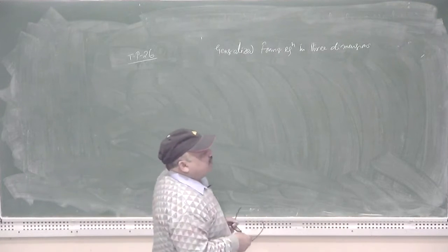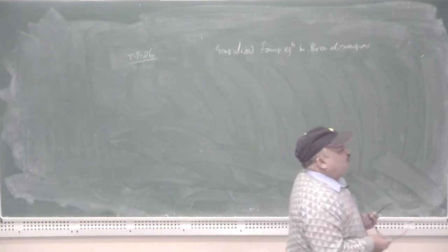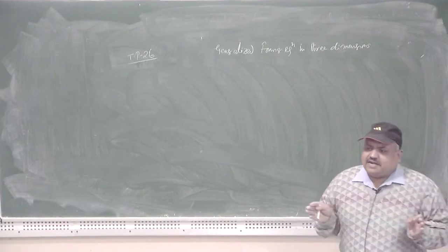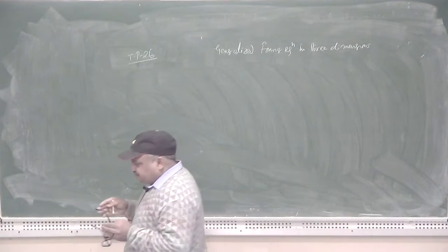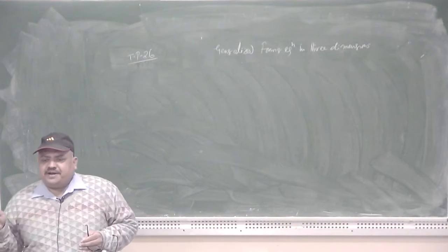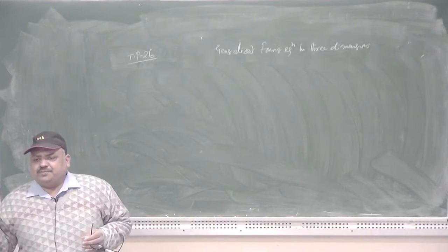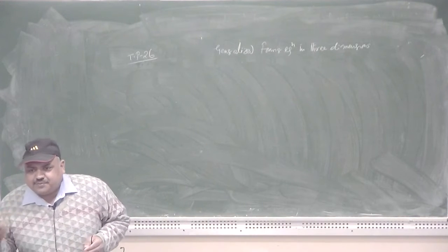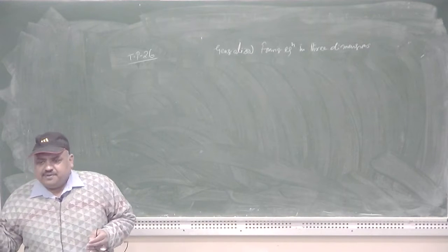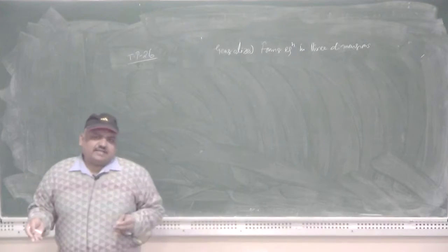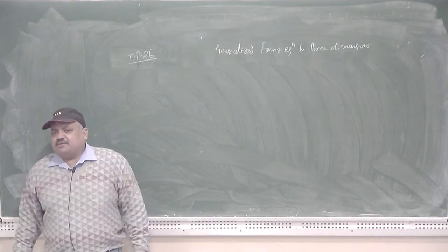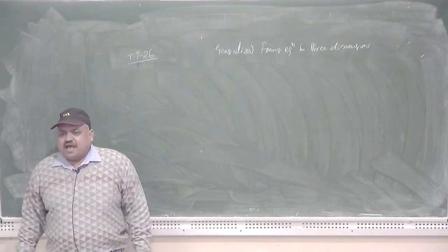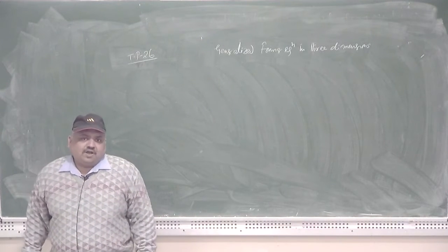In the case of spherical polar coordinates, only the radial direction is considered and the dimensions along the theta and phi directions are supposed to be infinite, and hence the heat transfer along those directions may be neglected. Similarly, in the case of cylindrical polar coordinates, the dimensions along the theta and z directions are considered to be of that magnitude.